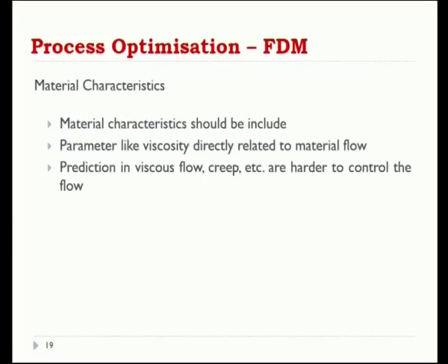Say, for example, there is a clog and the material is going to be at that temperature for more time. What will happen? Likewise, we need to work with the material characteristics as well. Say the melting point may be 100 degrees Celsius or 200 degrees Celsius. If the material keeps on melting, or stays idle at that temperature for a few minutes more than normal extrusion, then this may lead to an internal change in material characteristics, and there may be an entire change to characteristics which are not suitable for the product which is going to be developed.